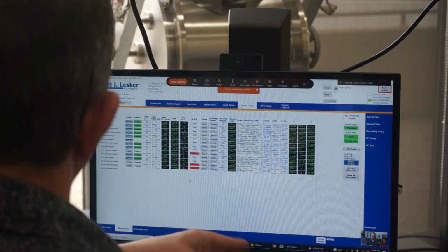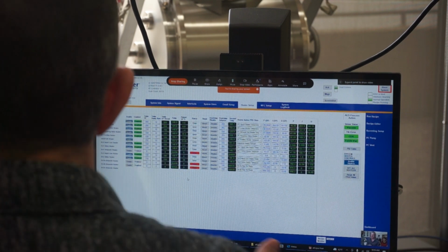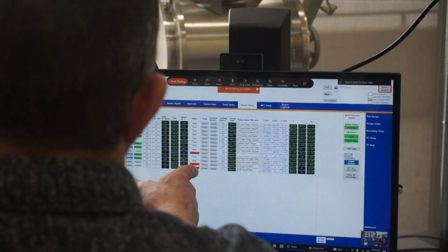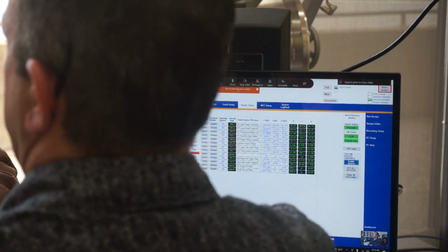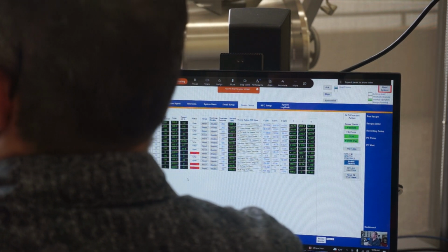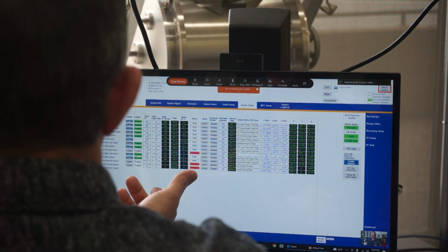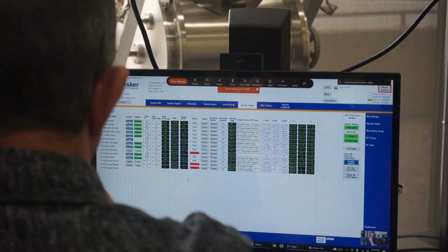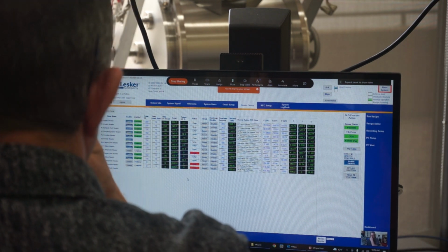Whenever we go into doing a little bit of training with the ampule heater, we'll actually create errors by plugging the thermocouple in and out. So if we unplug one of these thermocouples, I'll give you an example right now.